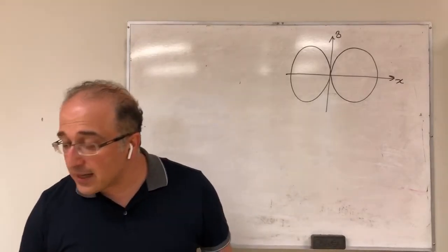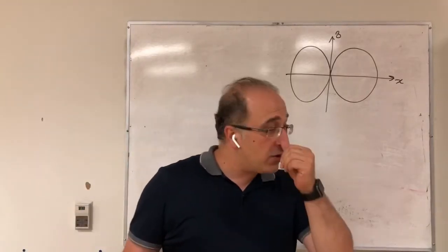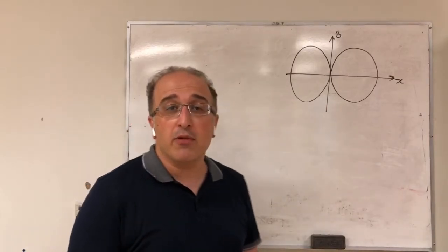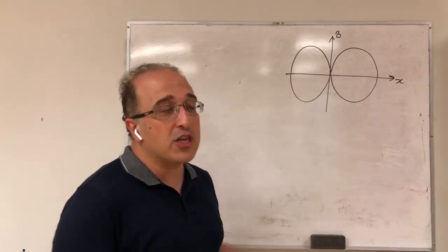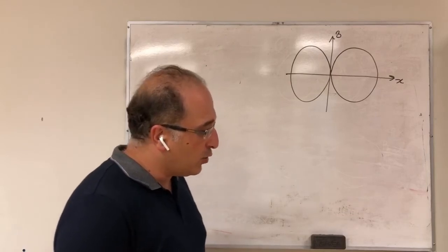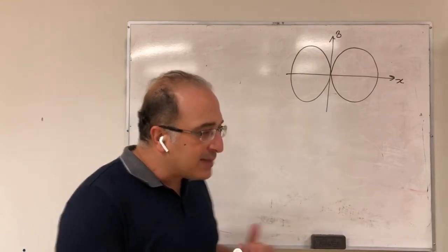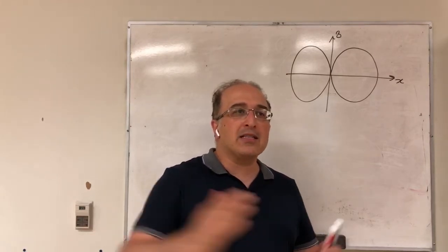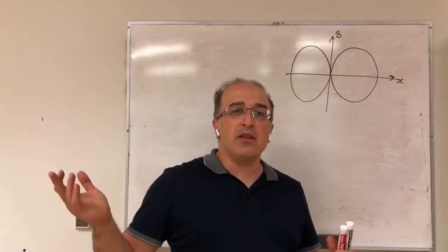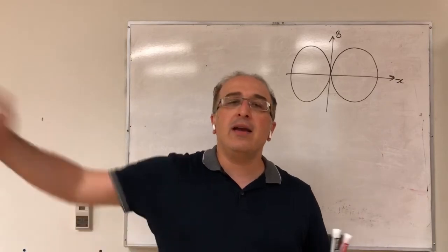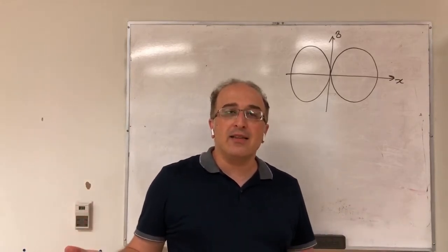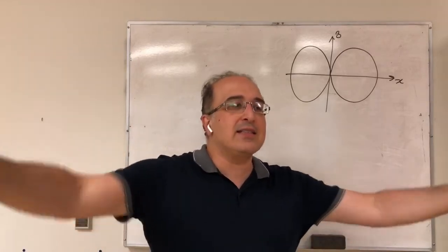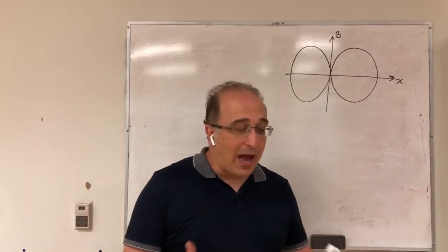At any distance that you measure, as long as you're in the far field, you get this shape, or a different shape for a different antenna, or pattern as we call it. And that's essentially why we call it pattern, because if I go X meters away, as long as I'm in the far field, or I go 10X, I'm essentially getting the same thing. It's like a pattern of the antenna that at any distance you see the same pattern.